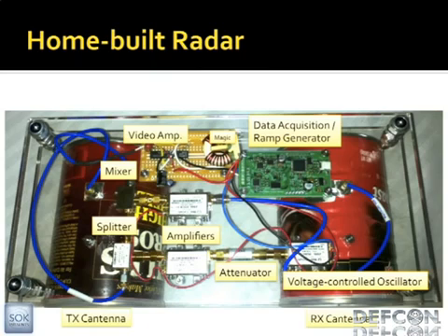Oh, so the reason that's there is because when I was trying to make this thing USB powered, I just wired it onto the power for this other stuff. Everything on here runs off of 5 volts. So I plugged the USB in, and the computer doesn't like that. It just turns off the port. The problem was the inrush current was too high, and I needed something to slow that down. So I was like, okay, I'll put an inductor in there. The only one I could find was this big choke transformer thing. So I just shoved that in there, and that worked. So that's all that's for.